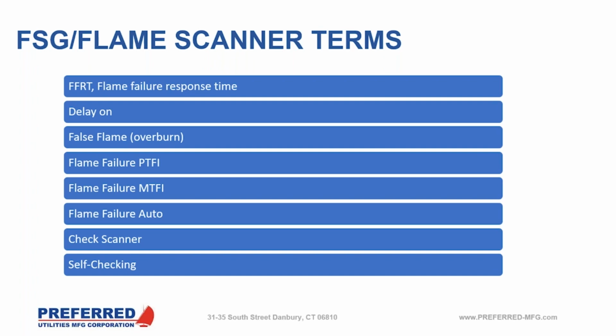This is important to understand, but it also can apply for gas fuel type applications where we may have a fuel valve that's actually starting to fail. It's extremely important to investigate a false flame shutdown or lockout in a flame safeguard, because we should not be seeing that at all. So it is very important to investigate this thoroughly.